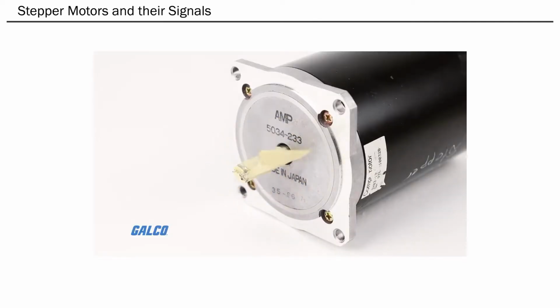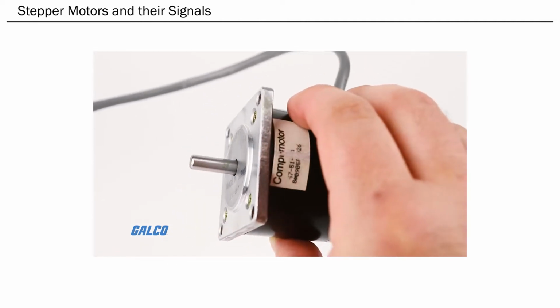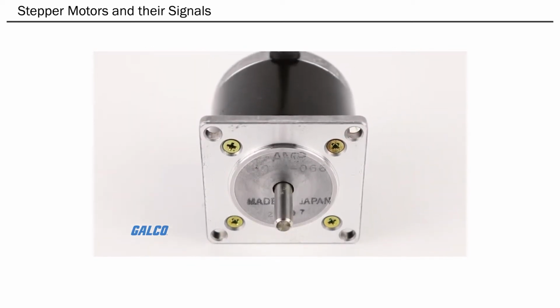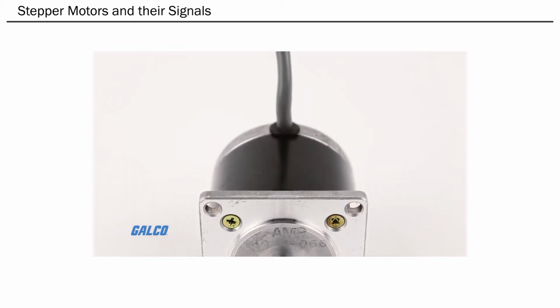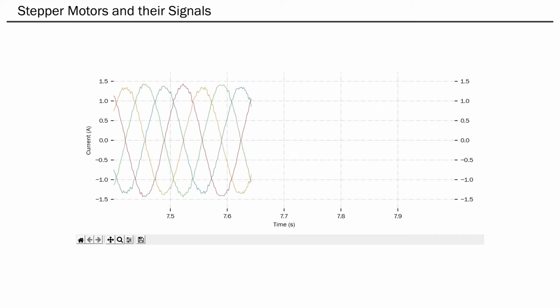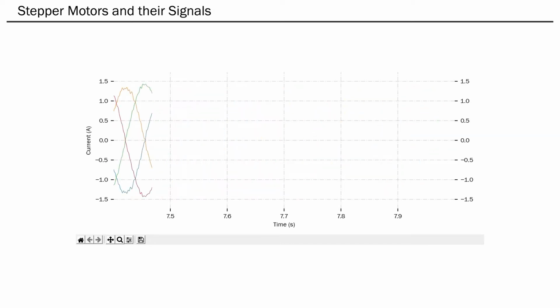Bipolar stepper motors are simple. 2 phases of current and a gear-like internal rotor. The movements this rotor allows are what give the motor its name. Instead of a smooth and continuous motion, the motor can step positions, ratcheting forward a fixed amount of rotation without any feedback control. Now, the stepper motor is a direct current motor, but for torque control reasons beyond our concern, they are typically driven by a sinusoidal current, which looks about like this. Each maxima and minima of the waves cause the motor to move forwards or backwards 1 step.